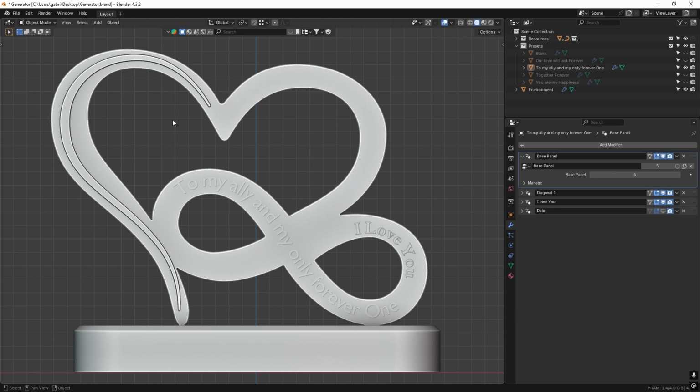Okay, to avoid this problem, so to allow you to take advantage of your build plate texture even with the decoration in relief, I made this version here, the base panel number 2, which has these little holes that will allow you to interlock the decoration you will print apart inside of this base shape, okay, inside of the panel. This way, this panel has a flat front surface, so you can print it facing down on the build plate, taking advantage of your build plate texture.